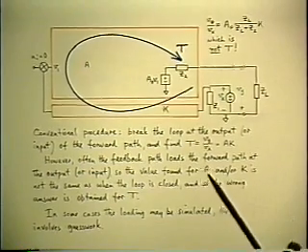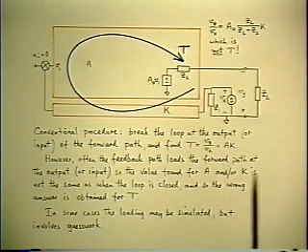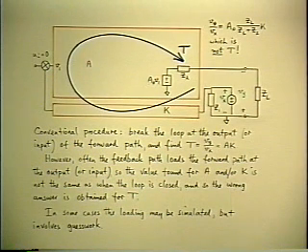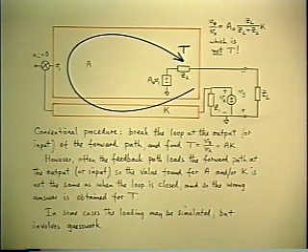However, we now have an alternative, because by reformulation of the expression for the closed loop gain, we've buried the A. So we don't need to know what A is separately. All we need to know is the total product T. So how can we calculate that and avoid this problem?